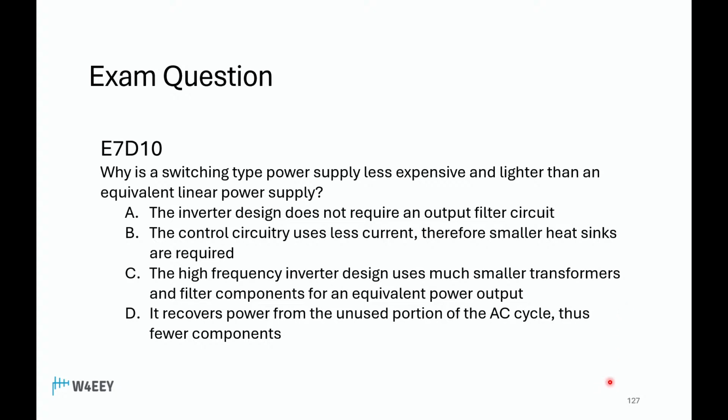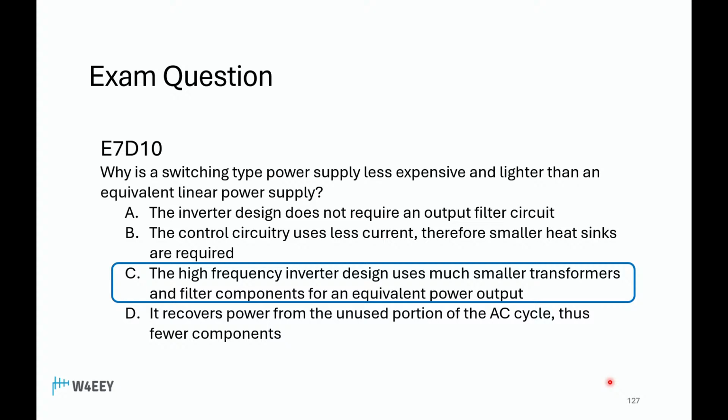Charlie, smaller transformer. We sure like Charlie tonight, don't we? Hi, Charlie. The high frequency inverter design uses much smaller transformers and filter components for an equivalent power output, and that's because they're running at much higher internal frequencies.